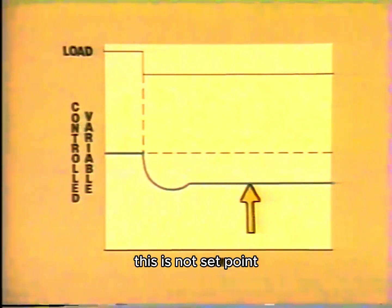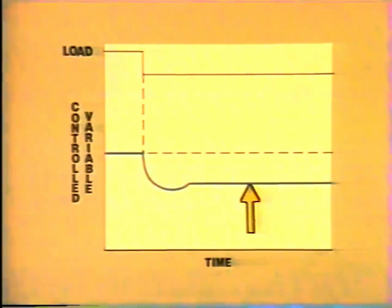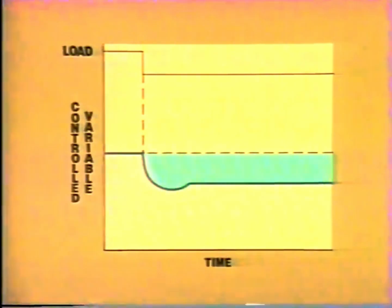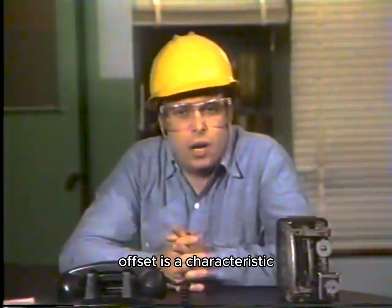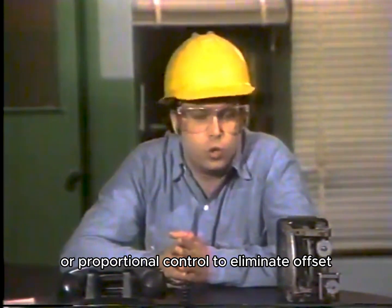This is not set point. It is a new control point. This dotted line is set point. The difference in the new control point and set point is called offset. Offset is a characteristic of a control system that has only gain or proportional control.